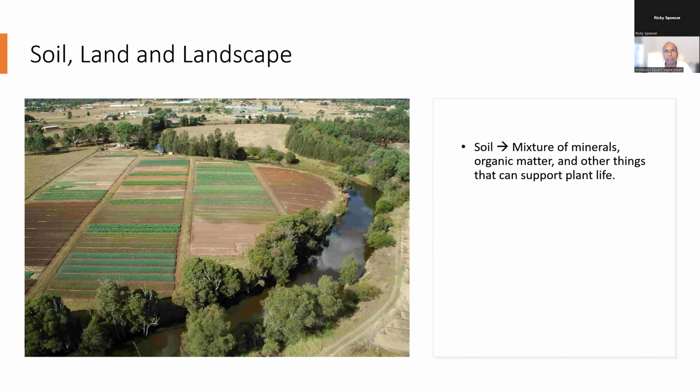So if soil contains, say, more than 70% clay, then it's called clay soil. And if soil contains equal proportions of these particles, sand, silt, and clay, then it's called loam soil. And sandy soil has a high proportion of sand particles, up to 80-90% sand. These particles are defined based on their size, the diameter of the particles. So clay has the smallest particles, and then silt is in between, and then there's sand.